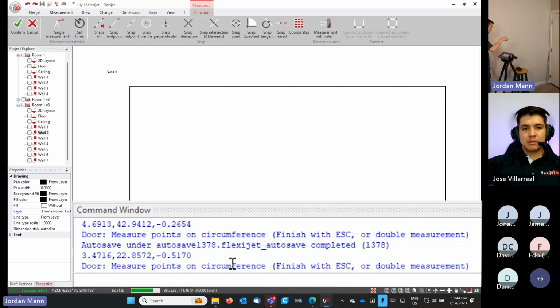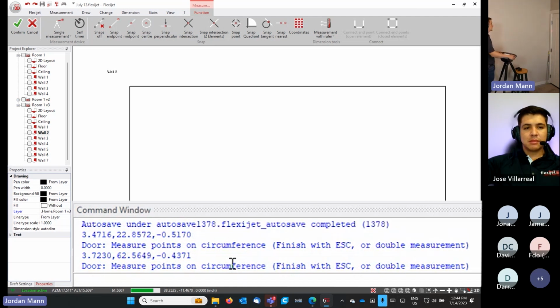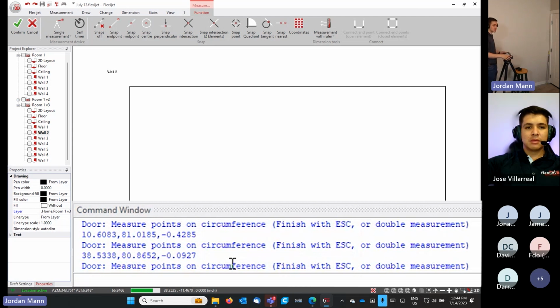We first measured a point on the hinge there. Now we're measuring points on the door itself close to the perimeter. You might be looking at this going, hey, that's not that accurate. You'd be better to get over there with the remote control on a target because you're measuring the edge of the door itself. You would be 100% correct. For the sake of this example, we're going with the easy way here.